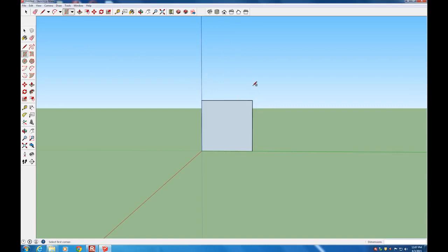So now we're going to add a back to the chair. I'm going to go over and click on the Line tool and start from this corner point. Notice it highlights the endpoint to show that it's inferencing off of that. Draw up vertically 0.5 meters. So draw in the direction you want to go, type 0.5, click Enter. And then from the end here, we're going to go over 0.1 meters, and then straight back down to the base.